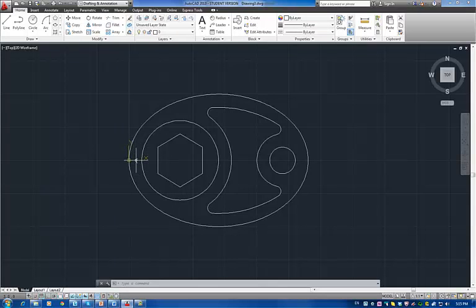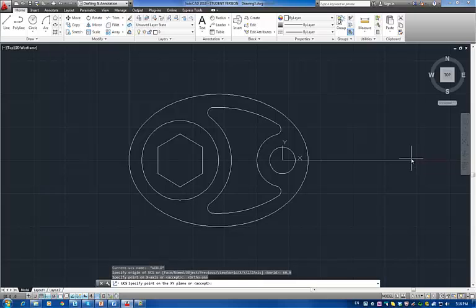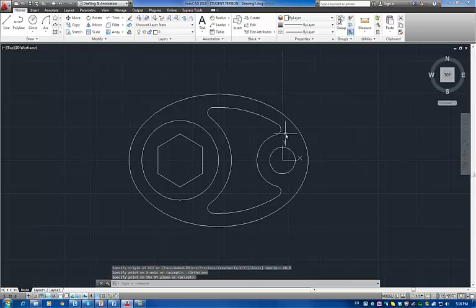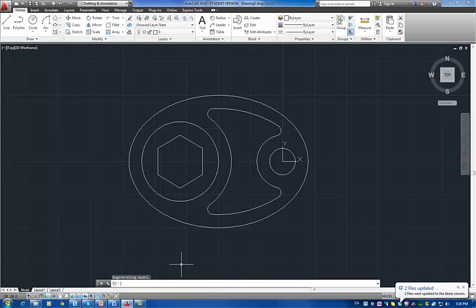This is the user coordinate system. You see now it's yellow. So I would say user coordinate system, and I would like to move it to another location, which is 60, 0. And then all you have to do is to locate X and Y. See, it's turning everywhere around. So I will turn on ortho and click somewhere to the right and click somewhere above so it's located, and I can move these. If I cannot move stuff, I can type regen from regenerate and then hit enter.